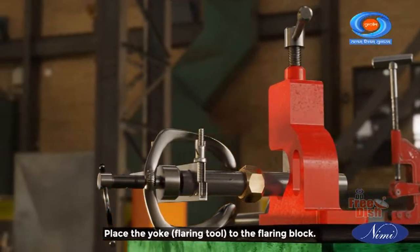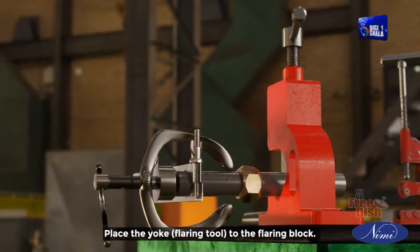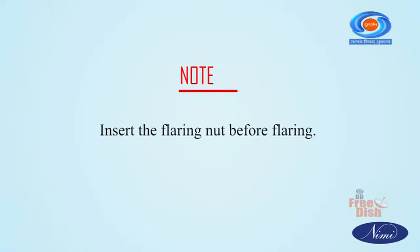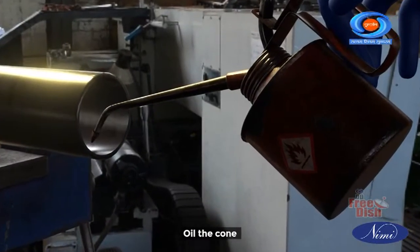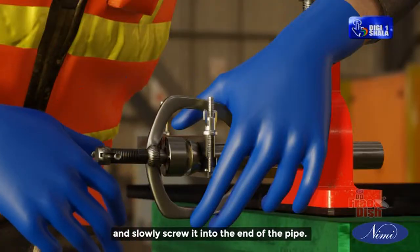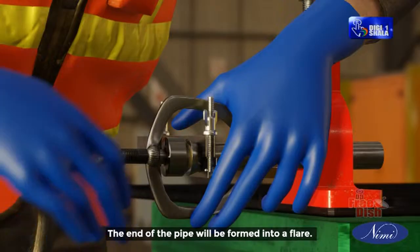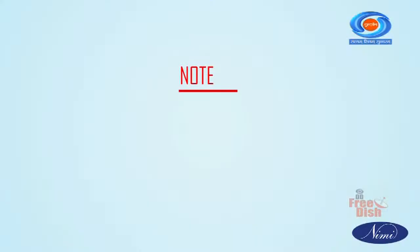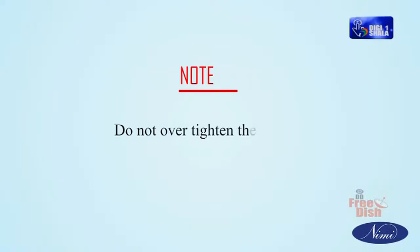Place the yoke, the flaring tool, onto the flaring block. Note: insert the flaring nut before flaring. Oil the cone and slowly screw it into the end of the pipe. The end of the pipe will be formed into a flare. Note: do not over-tighten the screws.